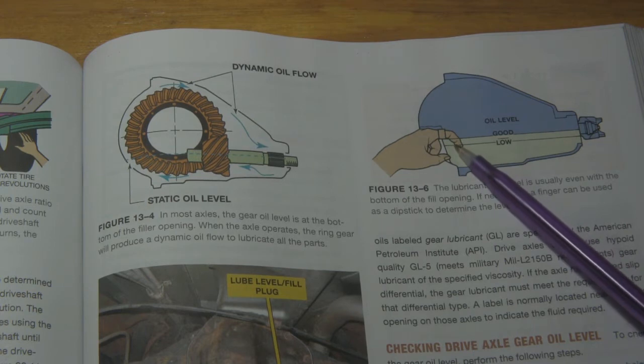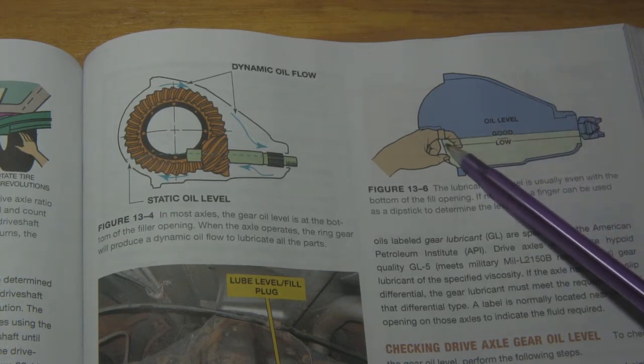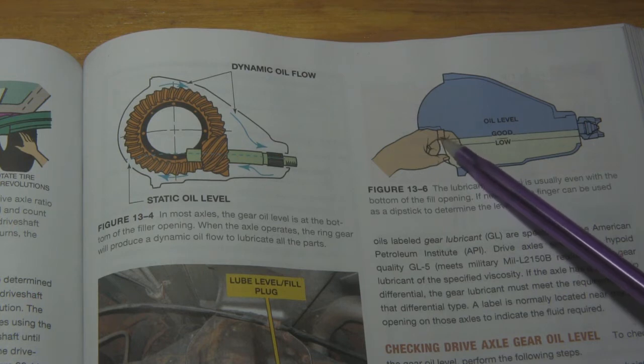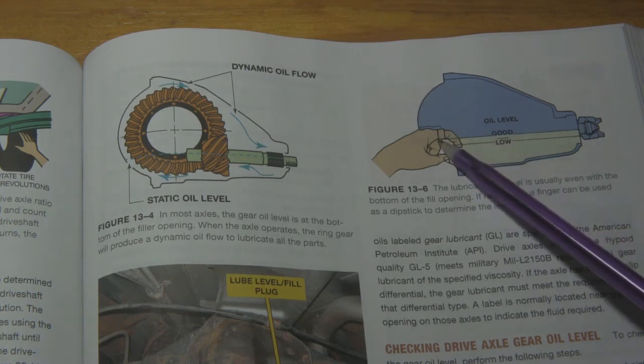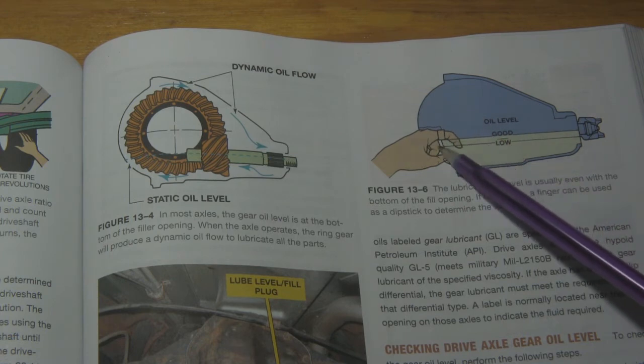And so some manufacturers, I've seen it, General Motors has a front differential, for example. There's a technical service bulletin out for it that says that by overfilling, and by overfilling what they mean is coming all the way up to that actual fill port. If you fill it up until it just kind of barely dribbled out, it's overfilled. It needs to be 1/2 inch below the fill mark.